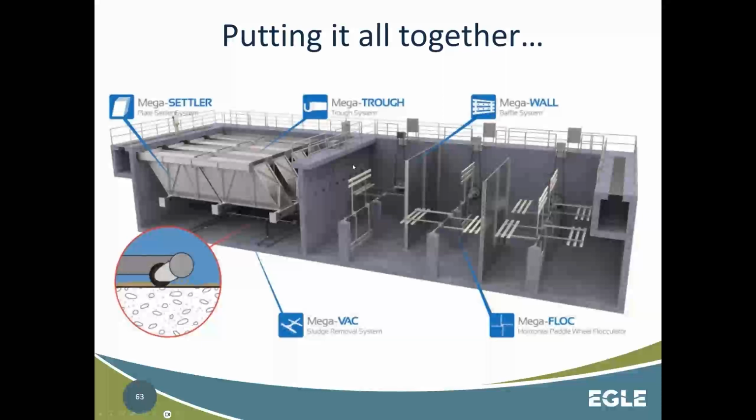A lot of times I've heard operators refer to this as a Swiss cheese wall. They put holes in the concrete wall at the end. It's going to help distribute the flow. Sometimes, if they know that they have more loading on one end of the wall than the other, then on the end that receives more loading, they'll make the holes or the penetrations smaller diameter, and then larger diameter on the low flow side. And that just kind of helps to equalize the flow into the next phase of the treatment plant. So pretty interesting. I think it's kind of fun to see different setups.